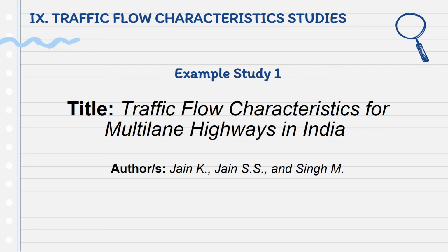In this study, we have two conclusions. One is that on the 6-lane carriageway, the traffic flow is quite significant as compared to the lane adjacent to the shoulder. And two, a close look at the speed-flow relationship, developed based on traffic speeds and flow in the outermost lane, reveals that the speed of vehicles on this lane is very low even in free flow conditions.